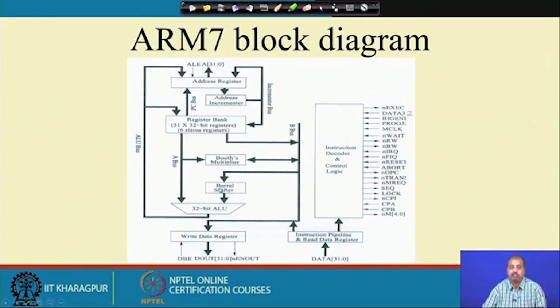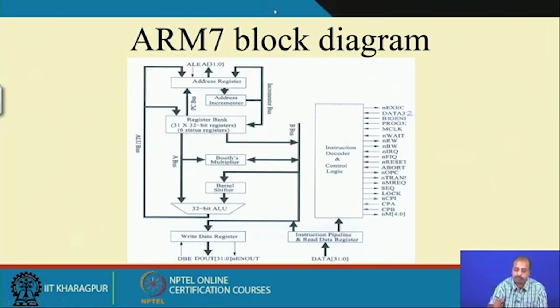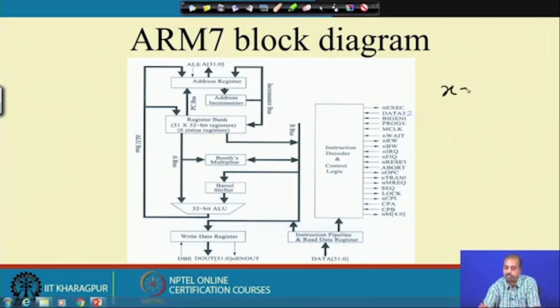The barrel shifter is used for shifting the bits of the operand. In one instruction, you can send the first operand directly, and the second operand is shifted by some bits. Like if you want to do an operation, say x = x + (y left shifted by 2 bits). In a normal processor, first you have to shift left y, and then say add x, y.